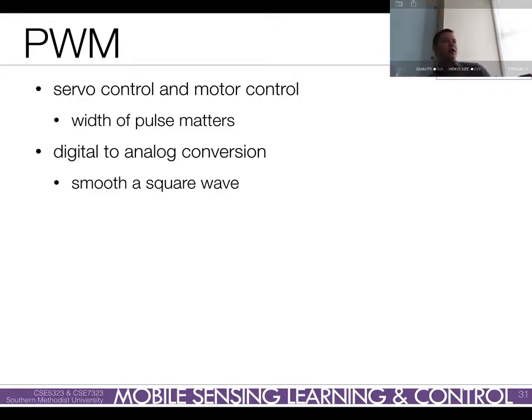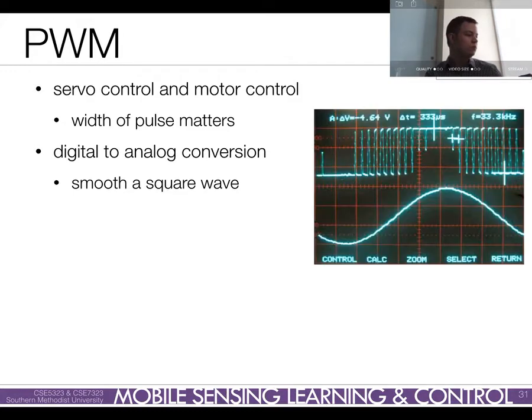Okay, so digital to analog conversion. This is how you do digital to analog conversion, by outputting pulse widths. Why? Well, essentially, you can output a square wave, and if you low-pass filter that square wave, you can turn it into a constant analog value on the output. You don't have to know why that is, but say you had a really, really short pulse width and you put that into a low-pass filter; on the output you're going to get a very small value.